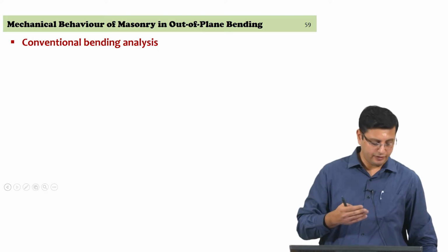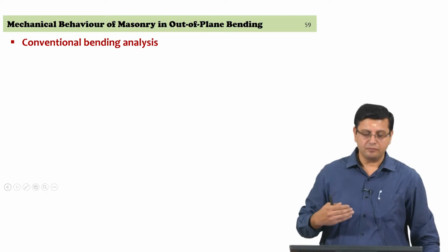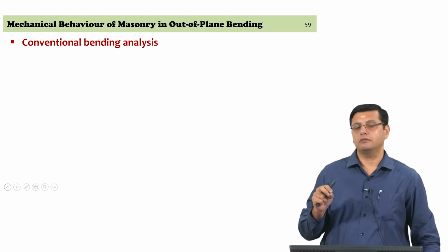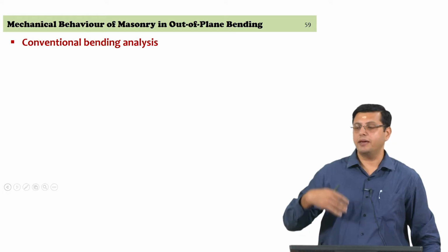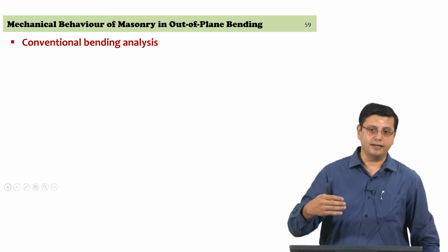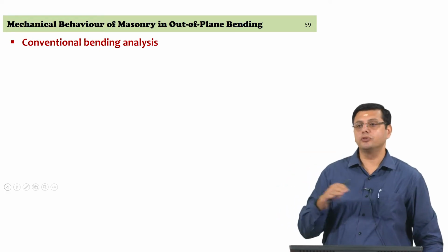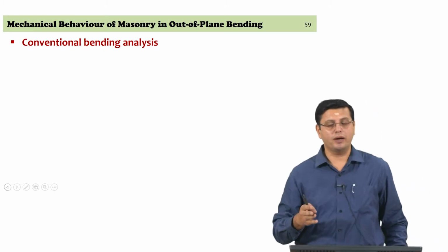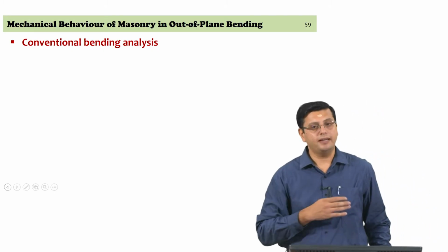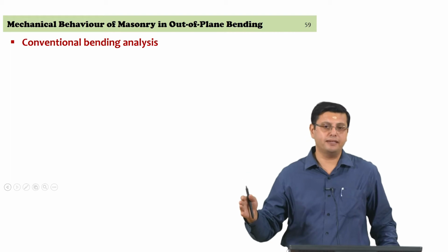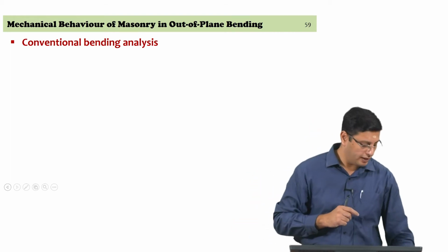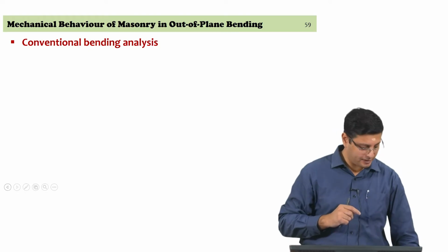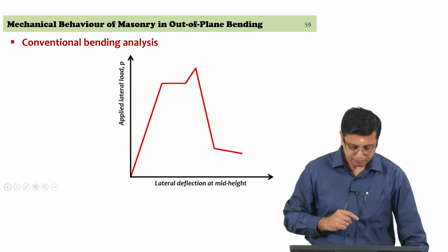displacement relationship based on introducing non-linearity in the way we want in terms of cracking occurring at the base and then cracking occurring at the mid height, but the section properties continue to remain linear elastic in compression. That was one approach. The second approach was again bending analysis, conventional bending analysis, but the section now is non-linear. So those were the two approaches that we looked at in the last lecture, and therefore to sum up, if